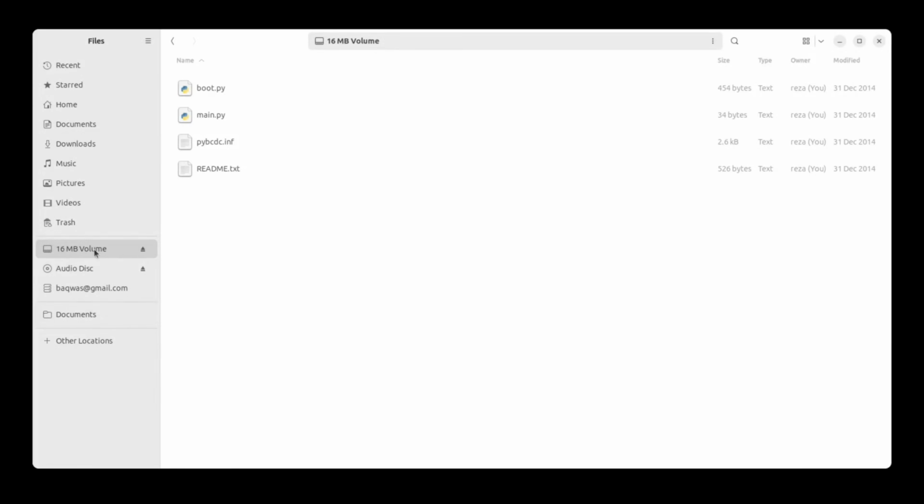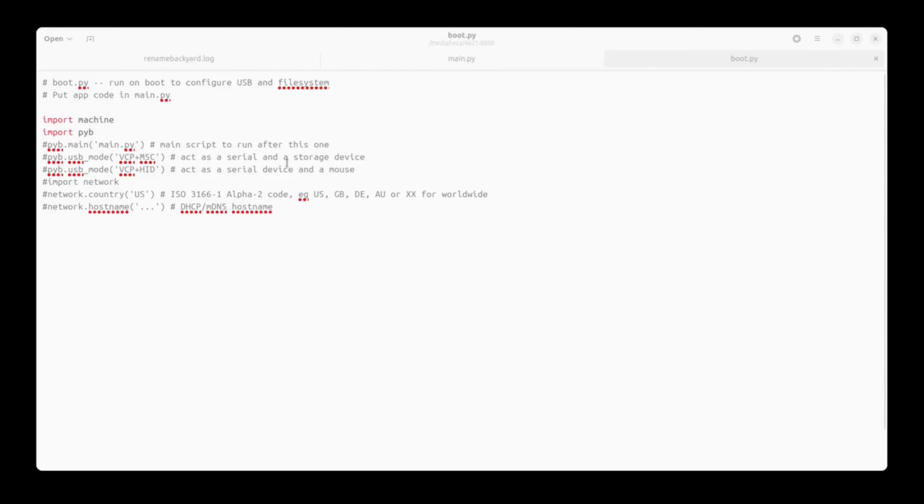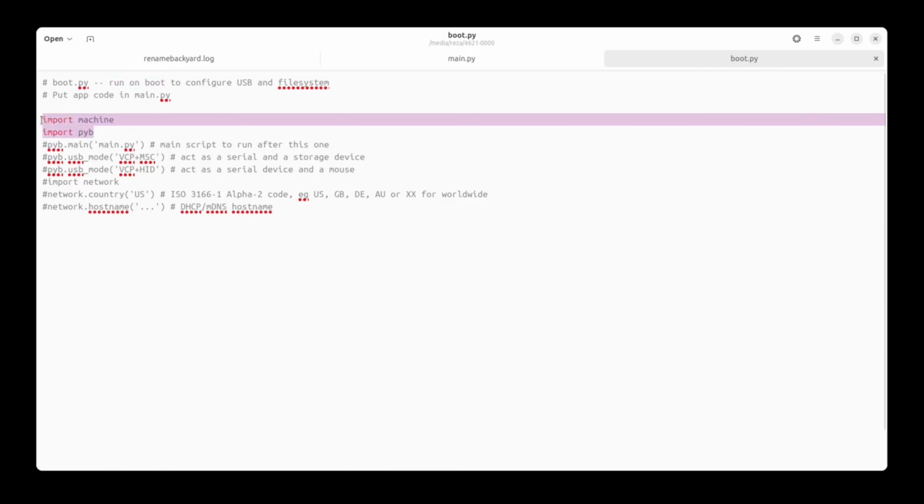After the board has been flashed, it is always a good idea to validate the operation. After flashing, the board is visible as a storage device under File Explorer. There are 4 files under the root folder of the board. If these 4 files are visible, then the board is ready to run MicroPython scripts.